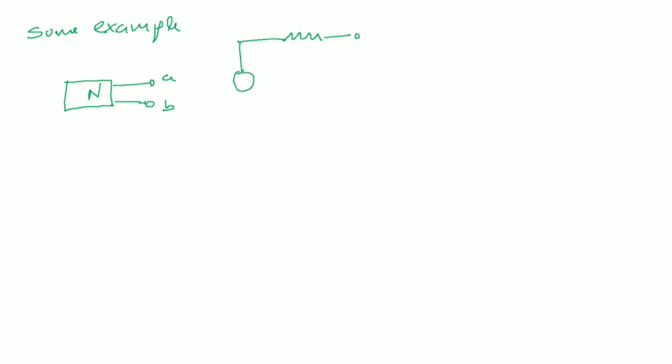So friends, I want to give some examples. We see a circuit. Consider the linear two terminals. You see the figure. The network may contain dependent as well as independent sources. According to Thevenin's theorem, network N, regardless of its complexity, may be replaced by the voltage source ETH in series with a resistor RTH, assuming that the sources in N are direct current, as far as the external terminals A, B are concerned.